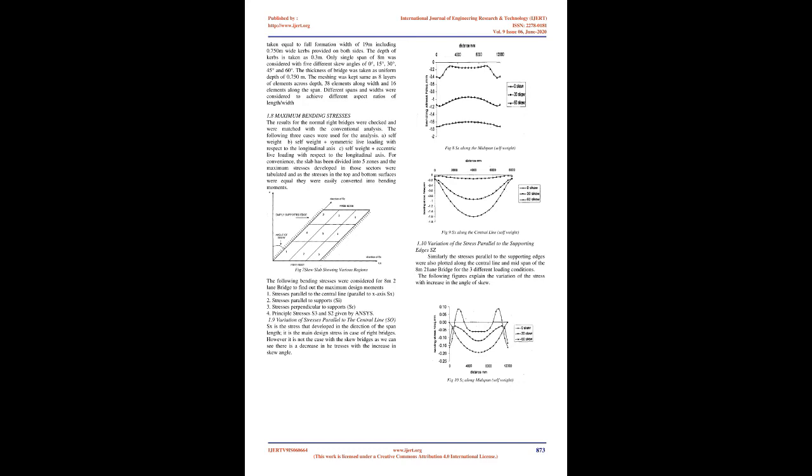4. The supports have been kept as simply supported, and for that the translation of the middle layer nodes has been restrained in the y direction only. However, to restrict secondary movements, the nodes at the other support has been restrained in z and x translations also.